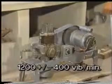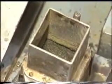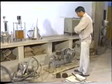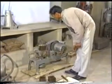This vibrating machine has standard vibrations of 1200 plus minus 400 vibrations per minute. The cement cubes are compacted by giving standard vibrations for 2 minutes. Switch off the vibrating machine after the stipulated time of 2 minutes.